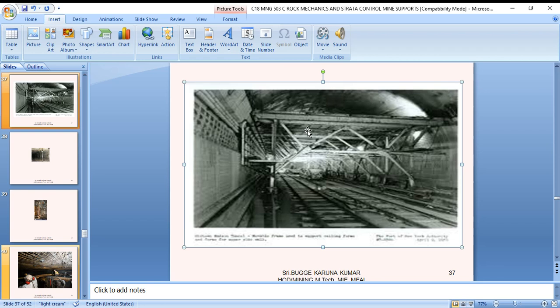If the sides are weak, the bar is placed on a vertical prop. If the bar is circular in cross section, the top end of the prop should be hollowed out to fit the contour of the bar. Alternatively, the bar may be flattened at each end so that the end can rest on the flat ends of the prop. The bar should always be tightened against the roof and should offer the maximum area of contact against it. The side of the bar towards the roof is chopped off flat for this purpose. Flat wooden loggings are also used if the roof is uneven.